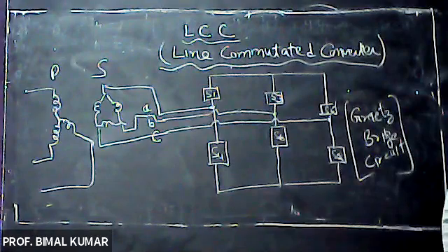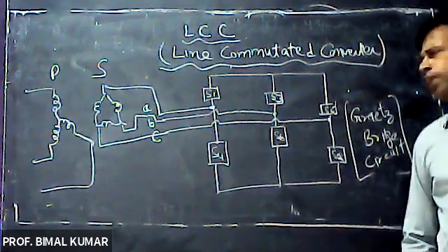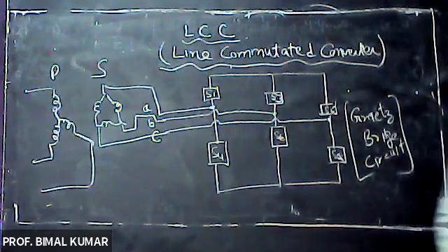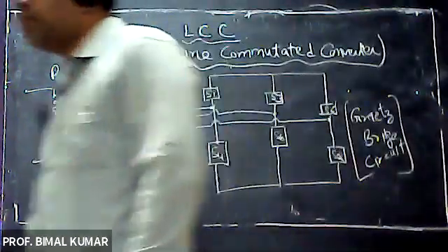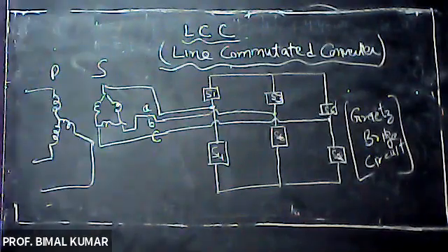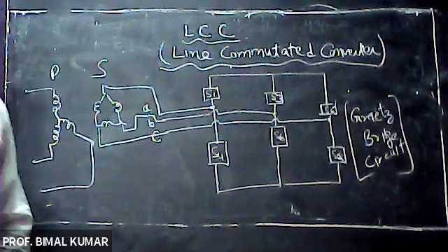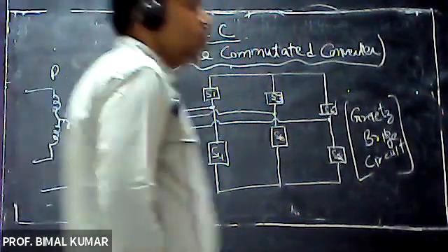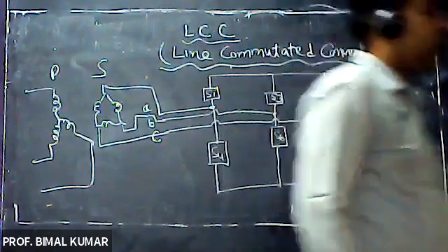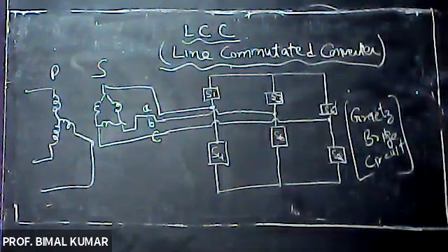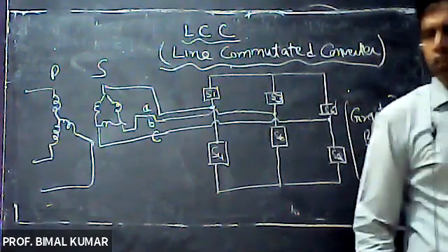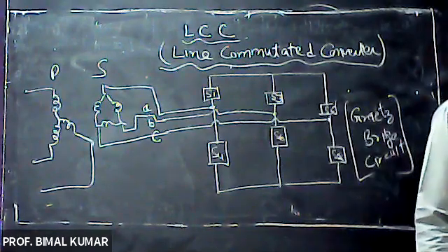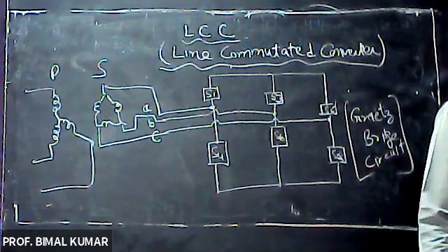In the case of LCC, because today I will discuss only LCC, these switches are made of thyristor, SCR, right? They are not made of diodes or any other types of semiconductor device. Here we are using thyristor valves,